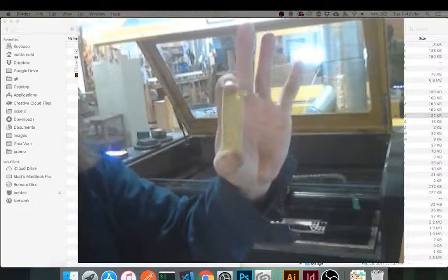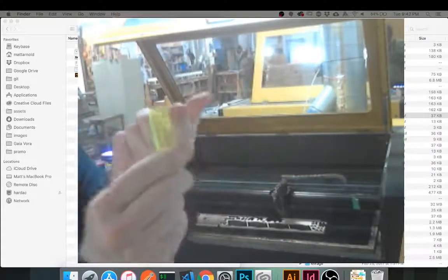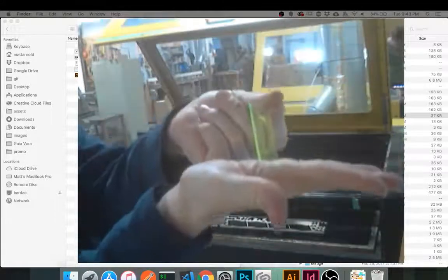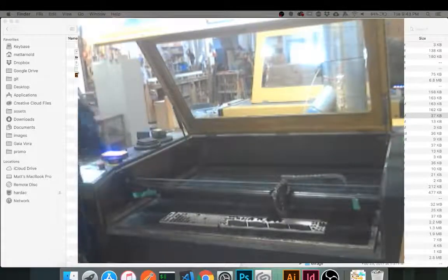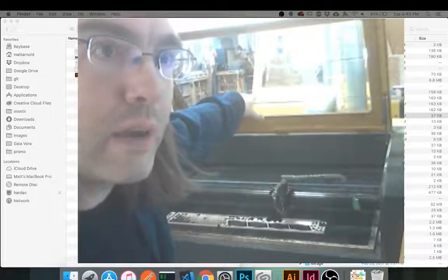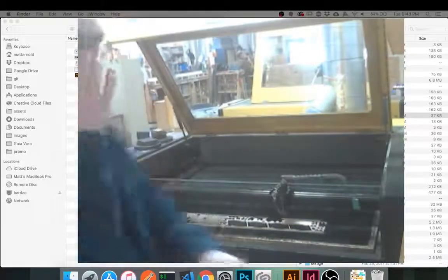And we just use this as a little cheat sheet. As soon as this touches the wood, and this is hooked onto the laser, then the focus is correct. Then we have another one, which is engraved with the word Wolverine on it, and that's for use on the laser over there, which is a different lens, so it needs a different distance.